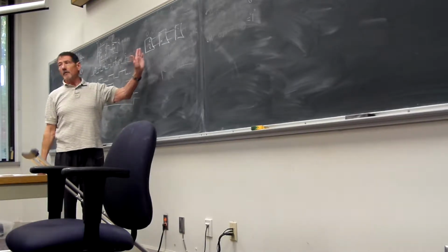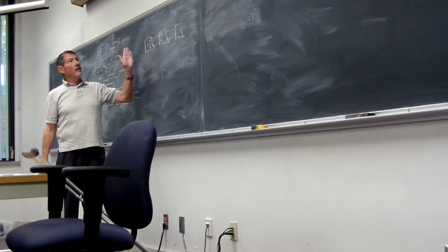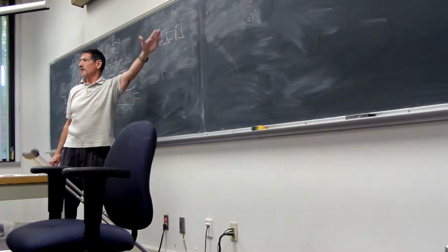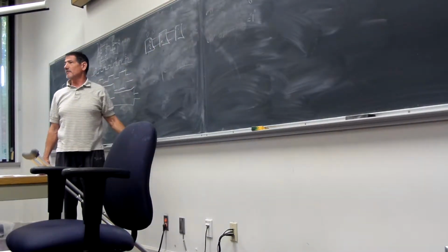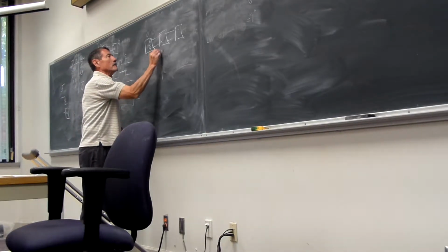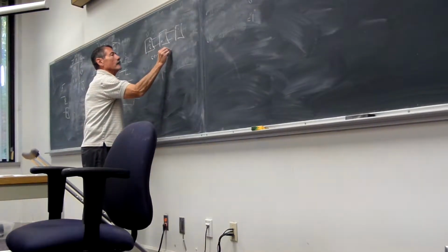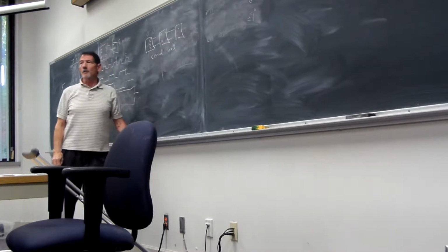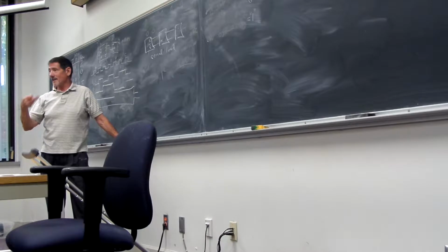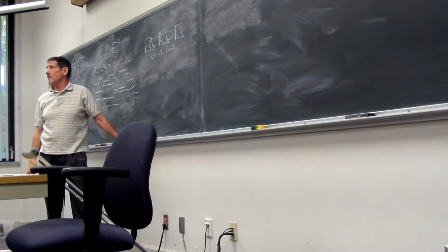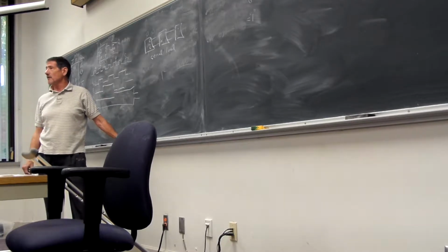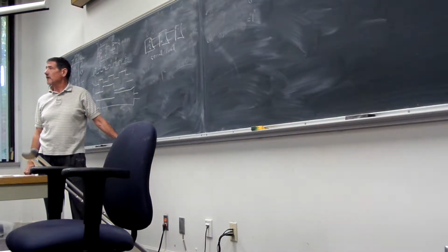Now what's going to happen, if they're all clocked the same, whatever gets here gets popped into the next one, then to the next one, to the next one, so this would be a shift register. So this would be a serial load. So I've got a 3-bit shift register shown there, but I could certainly make a 10 or a 20 or however many bits I need, and then serially shift in the information that I want.